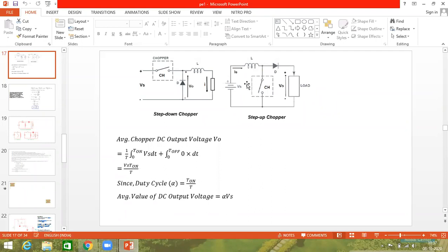So what is the first quadrant? First quadrant means if the motor is receiving the power from source to load, then it is represented as the first quadrant and motor is moving in forward direction. If the motor is acting as generator, with voltage positive and current negative, then it resembles the second quadrant. This is the imagination or conclusion of the engineers.